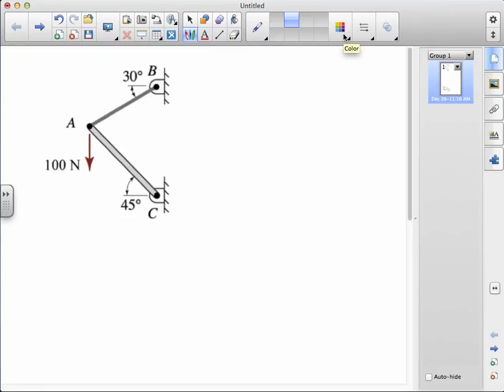In our first example, we have a relatively simple assembly consisting of a single cable AB and bar AC. Although bars, cables, and other structural elements have weight, their weights are typically negligible compared to the other loads they support. There are exceptions to this, but for now, we neglect the weight of these elements unless instructed to do otherwise. The other important feature of this schematic is the anchorage points at B and C. The small black dot is meant to indicate a pin or shaft that penetrates a pair of flanges that are then anchored to a wall.